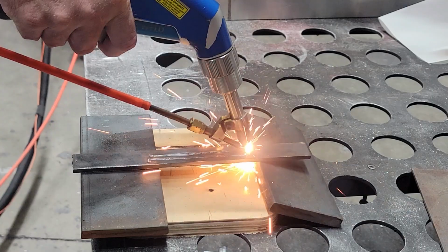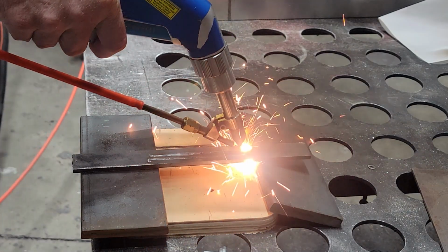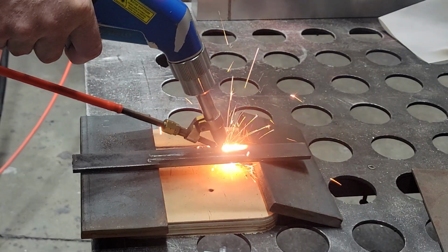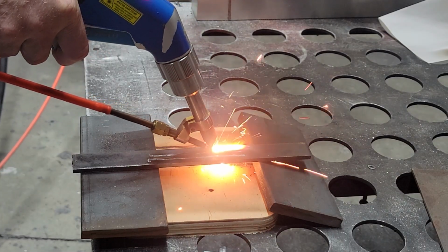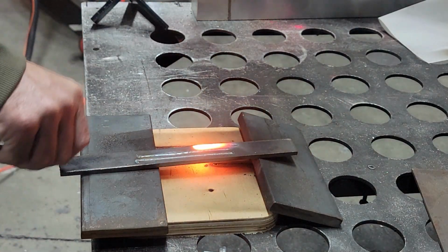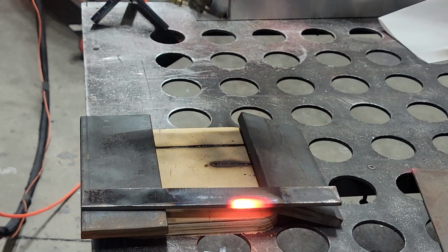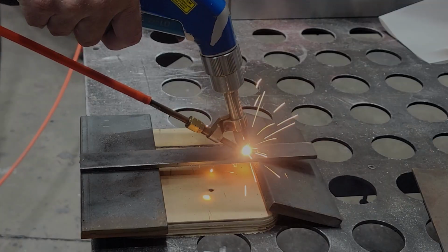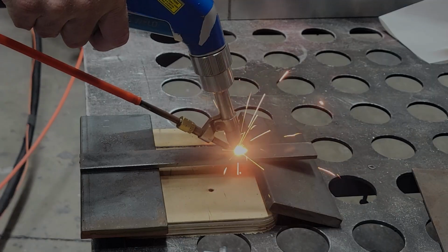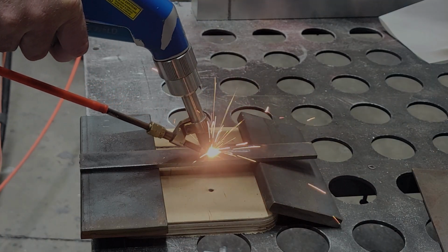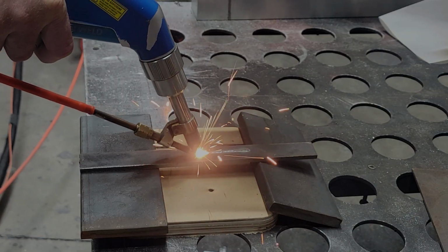Heat reality. Even though there's no ground clamp, the weld pool still obeys metallurgy. Too much heat: grain growth, soft metal. Too fast cooling: brittle martensite. Balance is everything. Handheld laser welding balances this issue. Controlled wire feed maintains steady travel speed, and when the process parameters are set correctly, overheating is avoided.